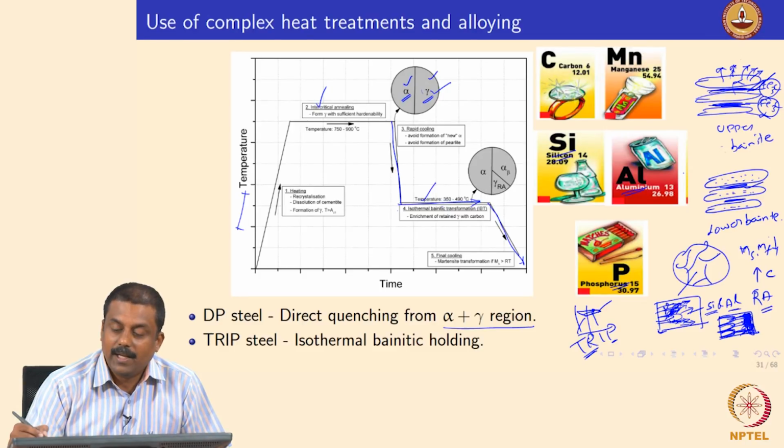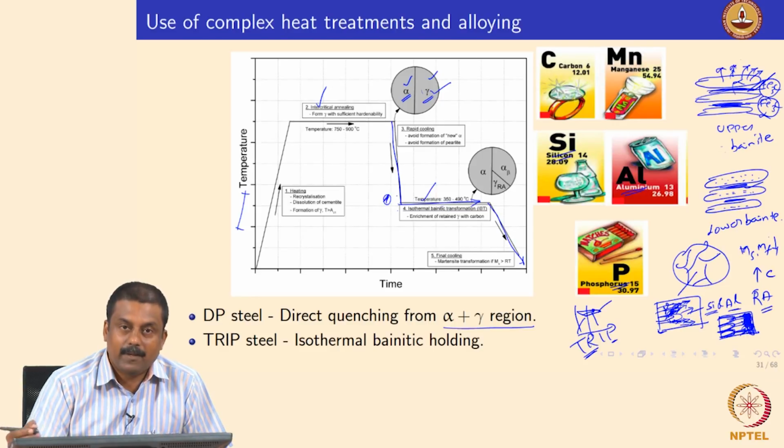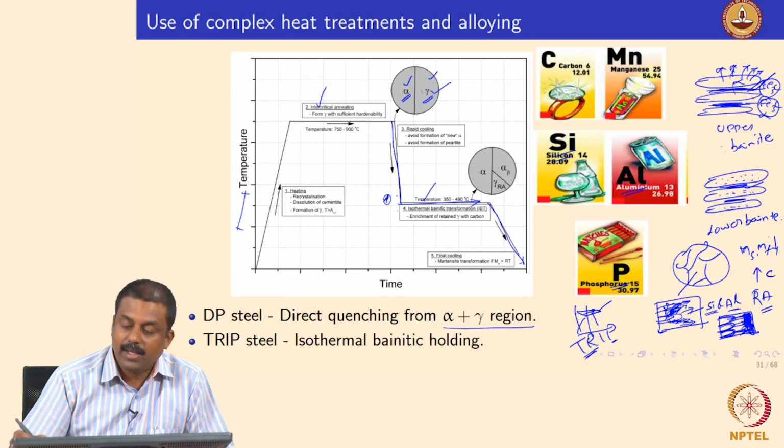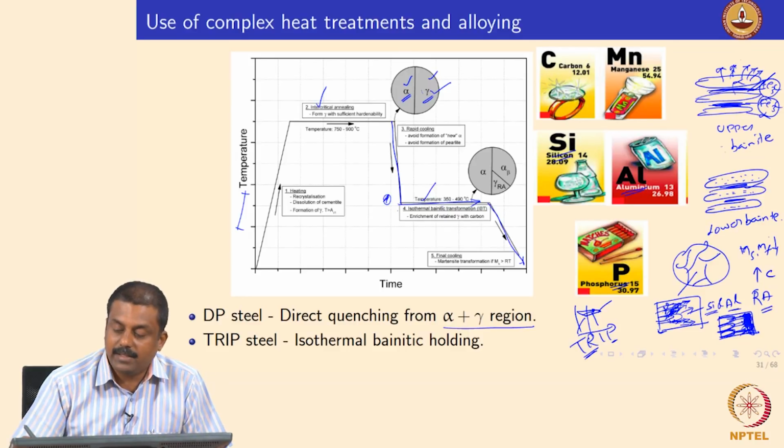If cementite does nucleate, the silicon or aluminum atoms should be pushed out, but the diffusion rate of silicon and aluminum at this temperature is very low. So, you barely move silicon and aluminum atoms to nucleate cementite. Therefore, when the bainite forms, it forms as a single phase, bainitic ferrite, without the nucleation of cementite.